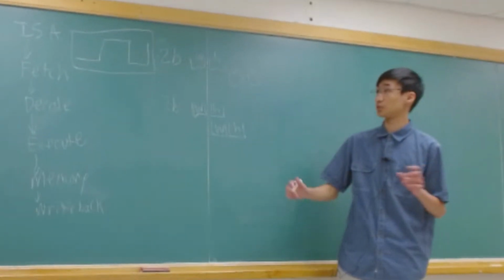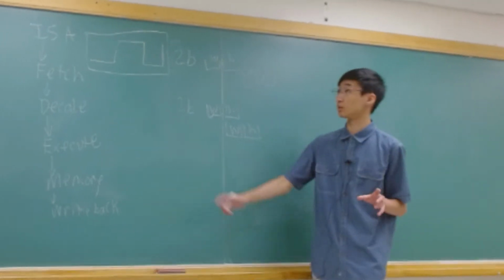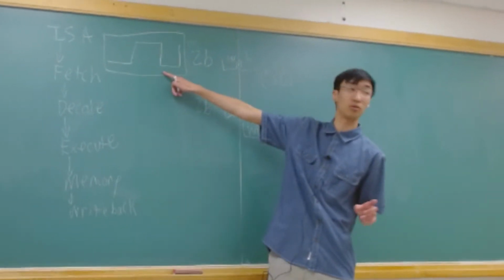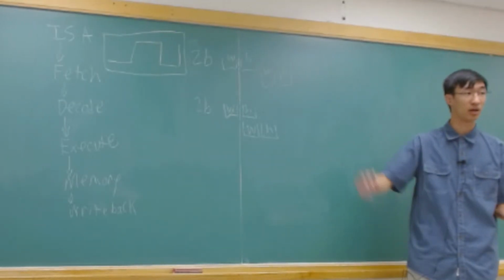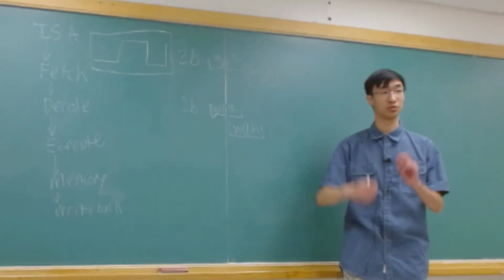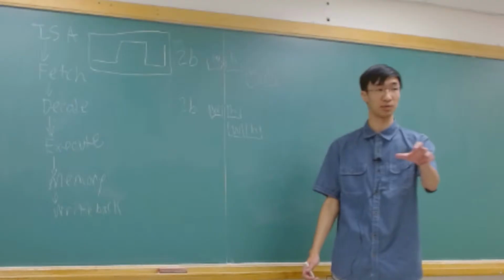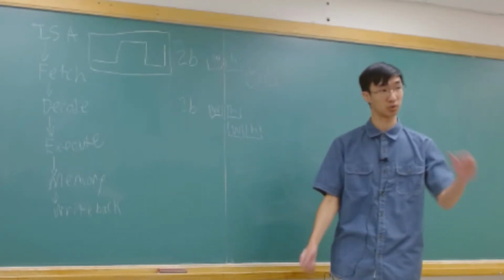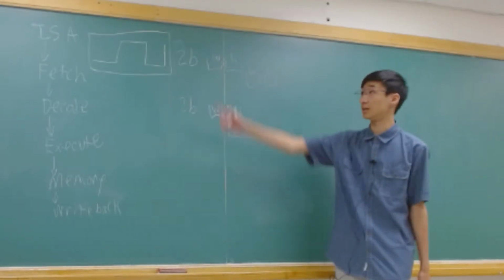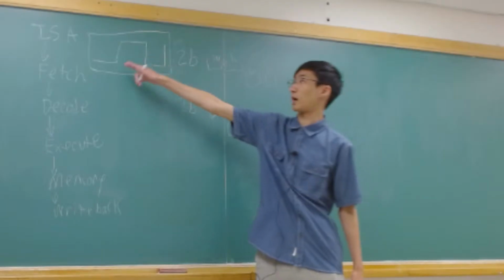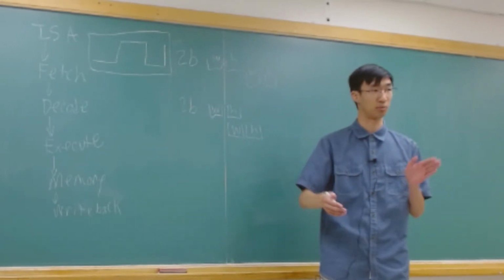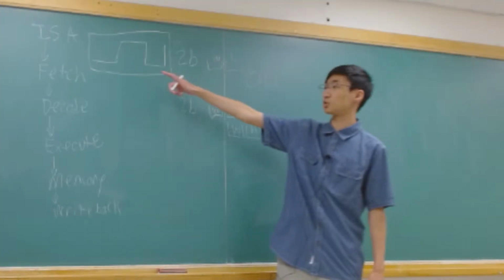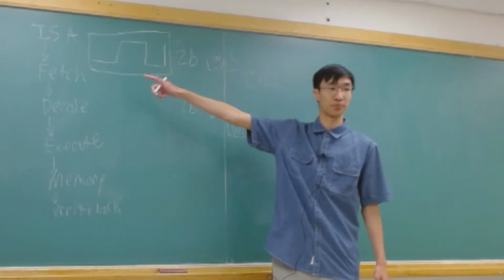If you ever see the word double data rate, it means that we're actually using the down clock, right? So we're using the rising edge and the falling edge of that clock cycle to actually do things. So if you have a double data rate chip, your DRAM, your DDR chip is doing a rising and falling data step. So it's doing it on both clocks, both sides of the clock. Your CPU will do it on the rising edge for the most part.